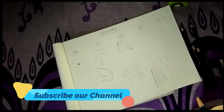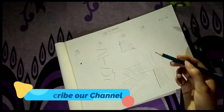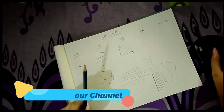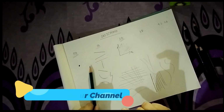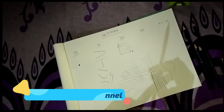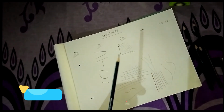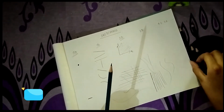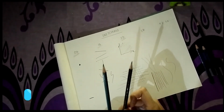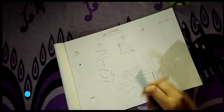Okay, so these are some basic exercises that will help you improve your drawing or sketching skills. Now, to understand the intensity of the pencils perfectly, there will be a stage in which you will be able to master all the intensity of the pencils with only one pencil, either HB or 2B. But I recommend using HB. I don't think 2B would work here. But using HB, you can create any intensity.